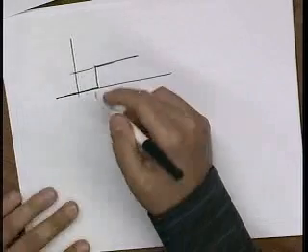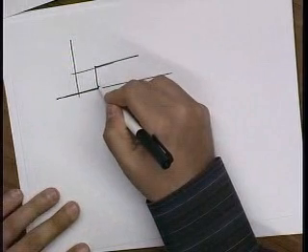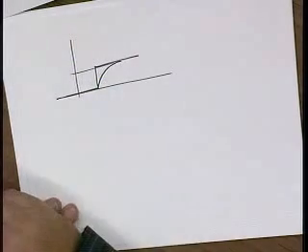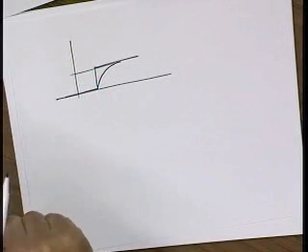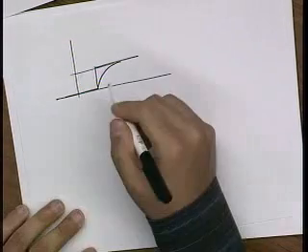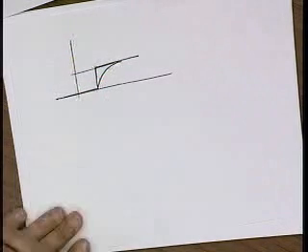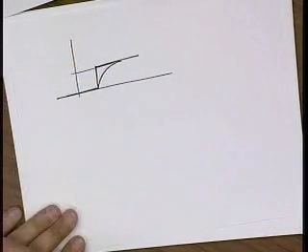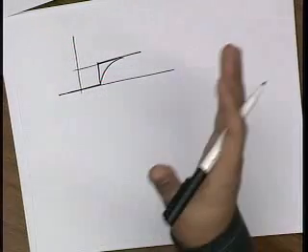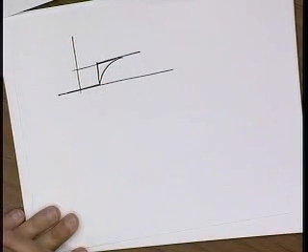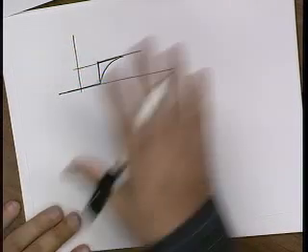In fact, if you first hook up your probe and you see something like this, your probe has a little place where you could put a screwdriver. What are you doing when you change that value of that capacitance? Well, actually, you're creating a zero, and you change it until you see a perfect step function. At that point, you've created a zero, which cancels the pole, and in fact, you get a very high bandwidth. Pretty cool, right? What's wrong with this approach?